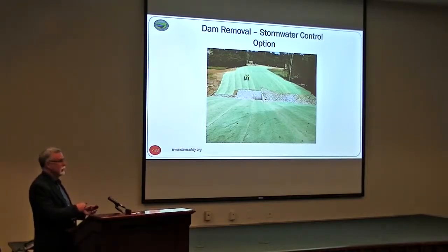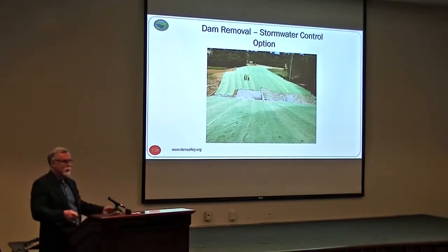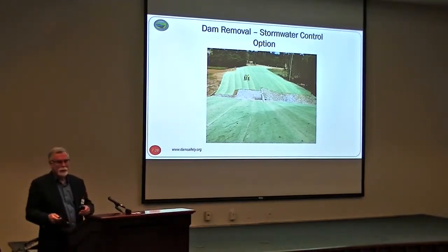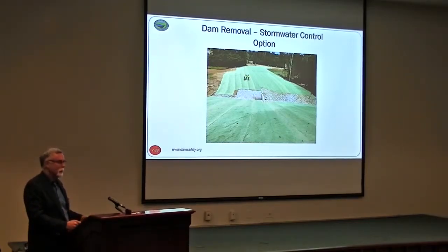Plus, you have to stabilize the old lake bed. It's now mud, and the environmentalists will say, hey, you can't allow all that sediment to wash downstream. But those of you that have owned lakes for a long time, you know if you pull your lake down for 6 months, the lake will grow up in weeds and bushes in a hurry. So what we normally tell owners is, before you breach the dam, drain the lake, wait a year and let the reservoir grow up with grasses and wetland, then breach it, because then you don't have to worry about the sediment because it's already been stabilized naturally.